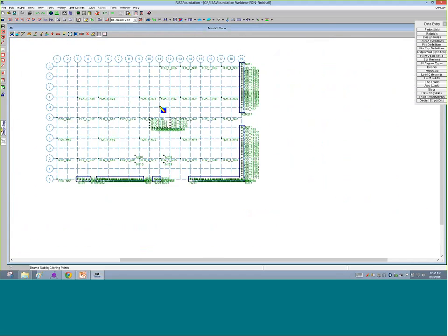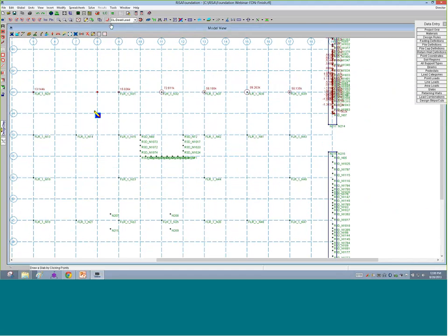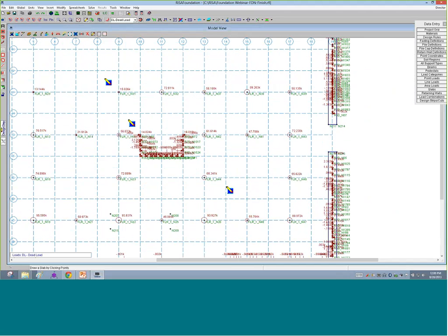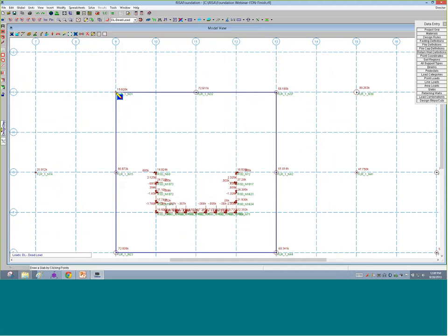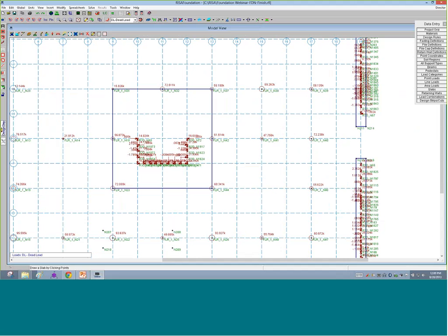Now in the center area, I don't have this drawn out, but one of the tools I have now is I can draw a slab directly to the nodes. So I know that I want to have a mat underneath my elevator bay and some of these outer perimeter columns. But it's just not realistic to draw a slab exactly to the location of a point load. That would fail obviously because of punching shear, and it's just not realistic.